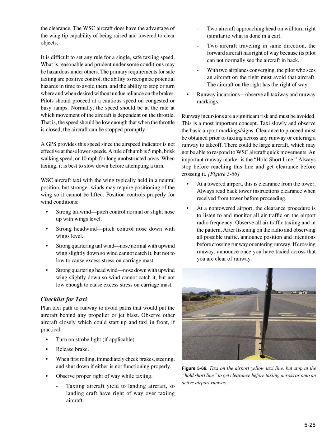Observe other aircraft closely which could start up and taxi in front, if practical. Turn on strobe light if applicable. Release brake. When the aircraft is rolling, immediately check brakes, steering, and shut down if either is not functioning properly.